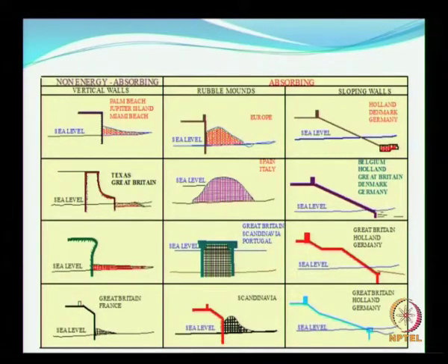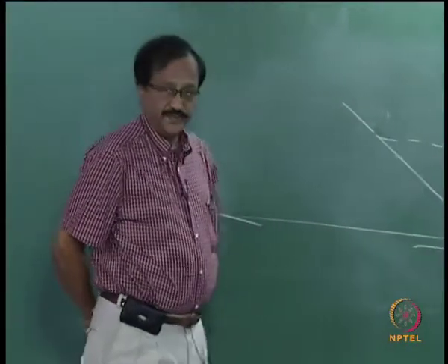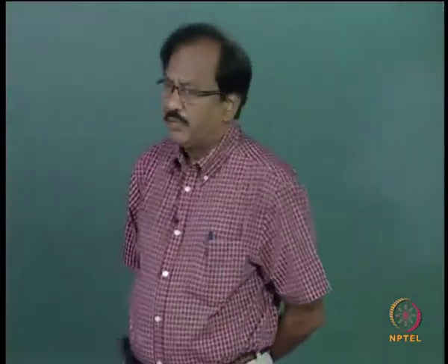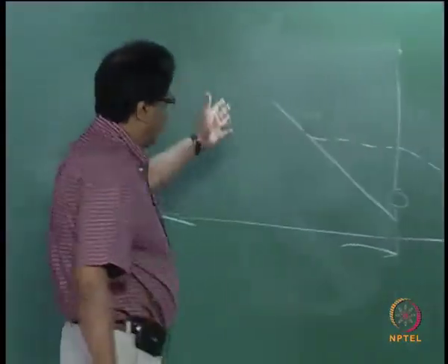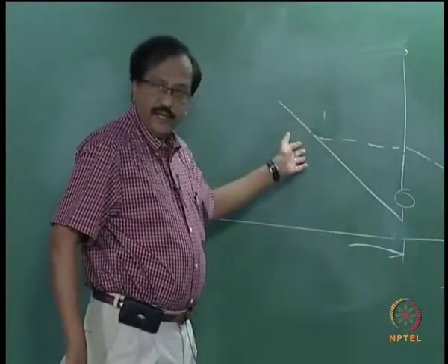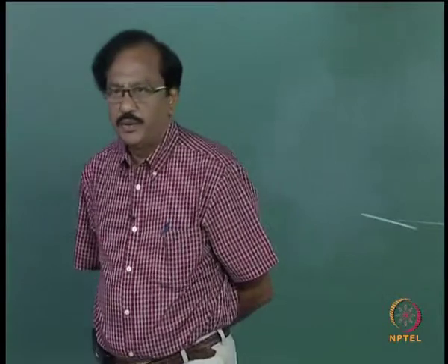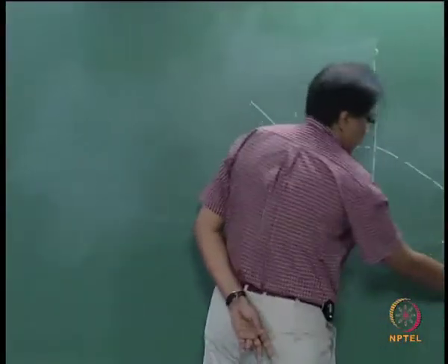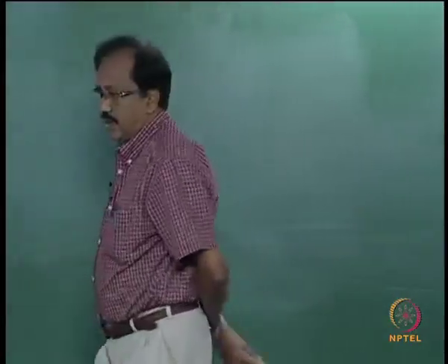So, you have to decide whether you need to have a berm, or you may not want to maintain a berm, and you want to go for a conventional breakwater or a seawall, and then make sure that regular monitoring is there, and if there are some stones being dislodged, you keep rehabilitating at regular intervals. So, hence this is based on the importance of the project for which this measure is being implemented.